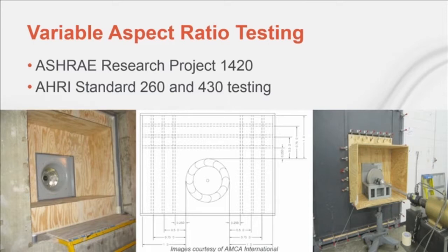Using ASHRAE test standards for airflow and sound performance, an air handling manufacturer can vary the parameters of an actual unit and optimize the fan and cabinet for each application. An air handler manufacturer can use this information to improve on the conventional rules of thumb and optimize equipment performance. Another option to consider is vibration isolation. A direct drive fan will offer results superior to a belt-driven fan, but vibration isolation may still be needed in some applications. With this in mind, let's discuss the various vibration isolation methods.